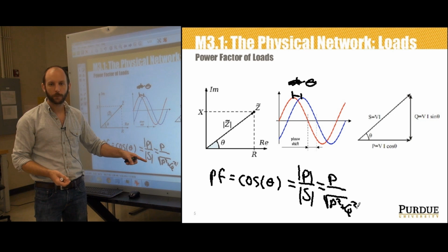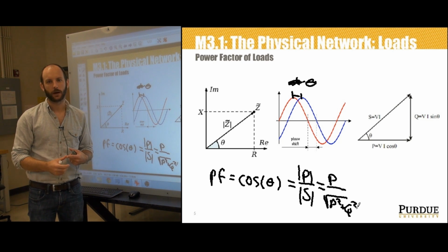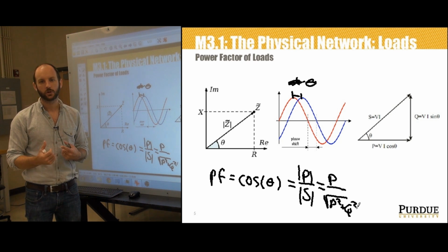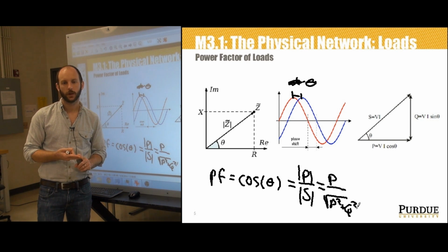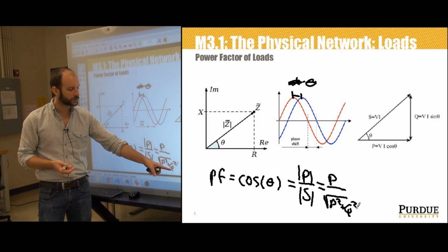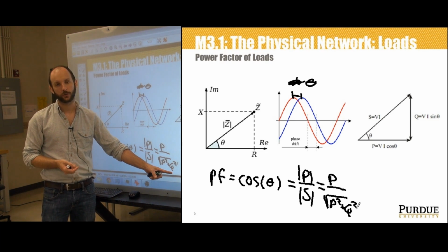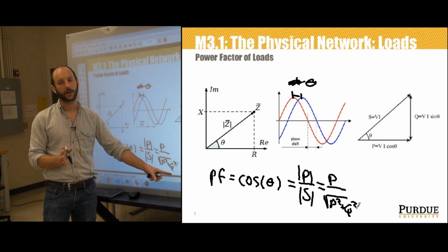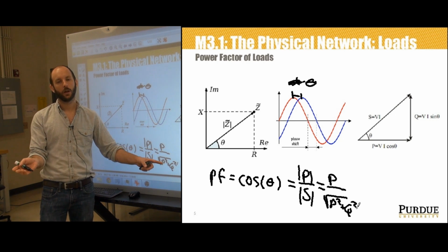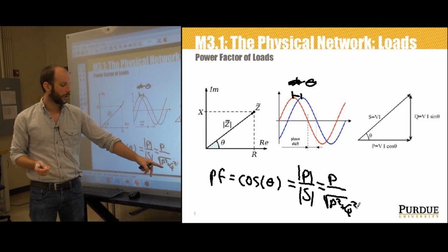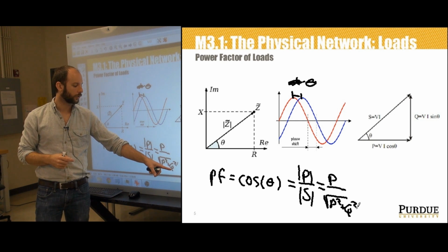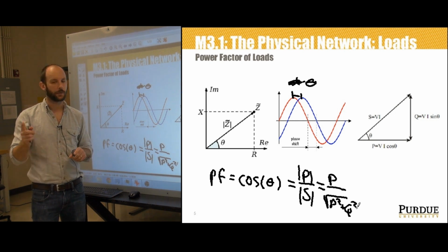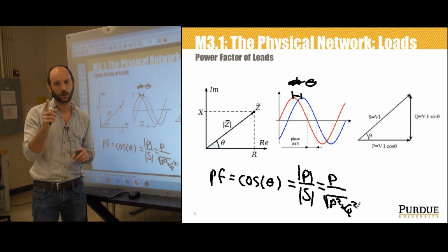Well, when there's a lot of apparent power or a lot of reactive power, there's additional loss in heat, right? Why is that? Well, I have to supply the current. Even though this Q is not doing real work, it does draw real current. Now that current oscillates between energy being sourced into the reactive portion of the load and being delivered back to the source by the reactive portion of the load, but that current is still flowing back and forth, that extra current component.